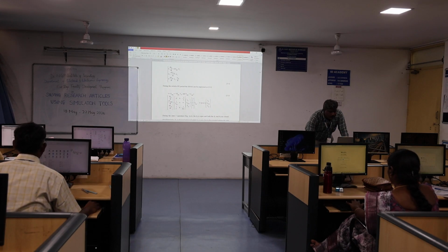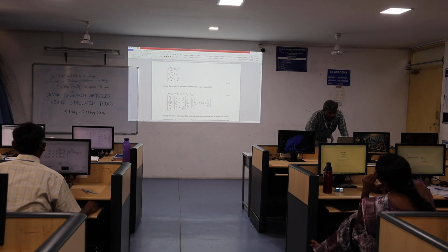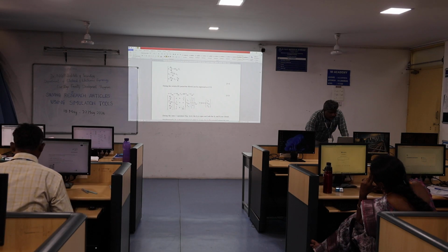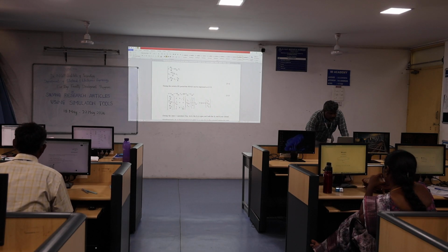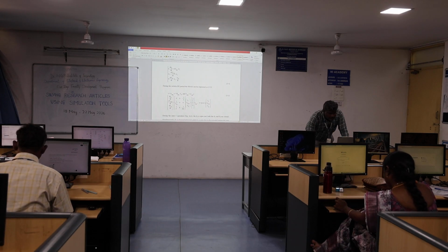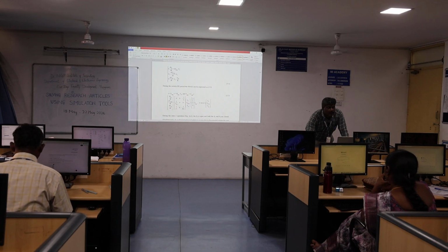If we multiply, dIL by dt is equal to minus 1 by L into V naught plus, coming to the input matrix, you have 2V in divided by L. So the input is 2 divided by L. Now you can apply this expression: dIL by dt is equal to 0, 0, minus 1 by L into V naught plus 2 by L into V in. So this is the first expression, right?